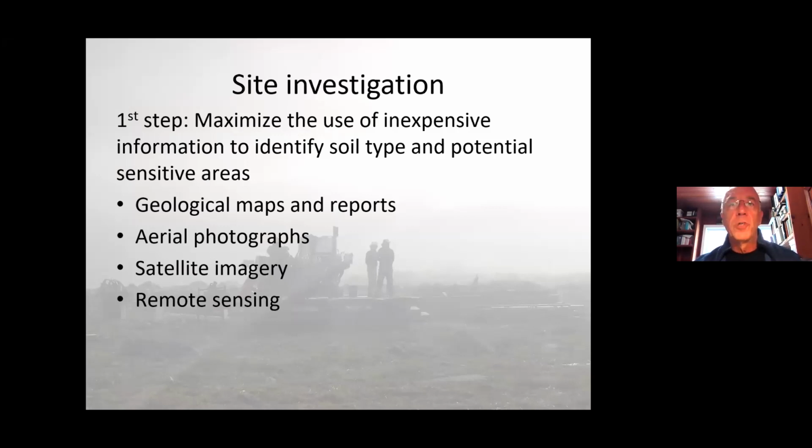It's difficult to do a good geotechnical study in the north because of the logistics of bringing equipment and doing some drilling, sampling, and geophysical studies. So you need to be smart when you do the investigation. You need to use a stepped approach. First step being to use as much as possible the information contained in inexpensive data sources to identify soil type and potential sensitive areas.